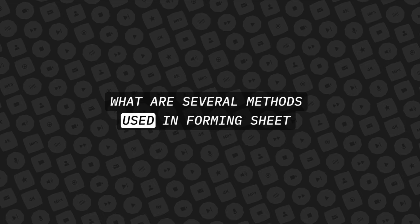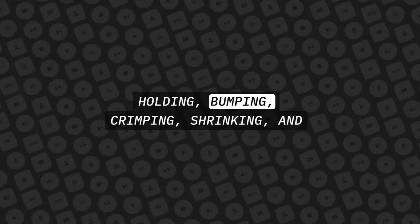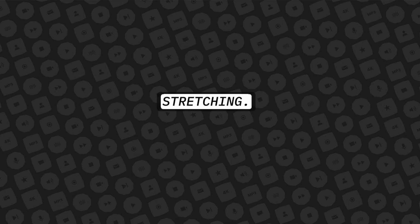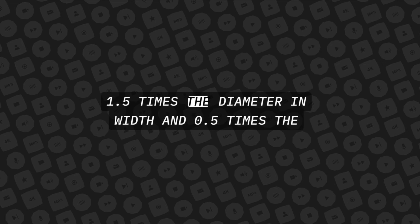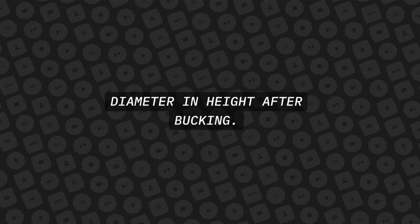What are several methods used in forming sheet metal? Folding, bumping, crimping, shrinking, and stretching. What kind of metal forming is done by bumping? Compound curves. What are the proper dimensions for the shop head of a rivet? 1.5 times the diameter in width and 0.5 times the diameter in height after bucking.